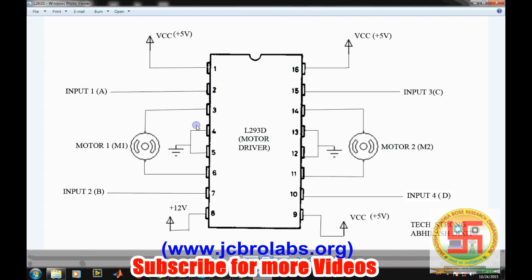That means if we want to enable this particular port of the driver IC, 1 needs to be connected here. Similarly, if we want to enable this other port of the driver IC, 1 needs to be connected here, and then plus 5 V supply is also connected to pin 9 of this driver IC. Pins 4, 5 and 13, 12 are connected to ground. So it has 4 input pins, pin number 2, pin number 7. This is one port and this is another port.